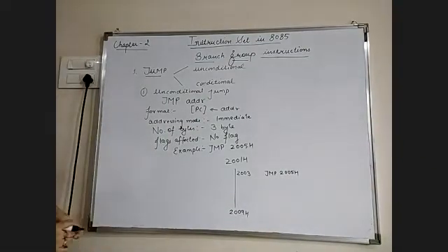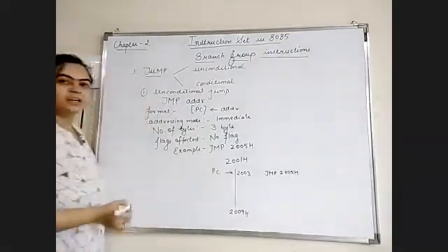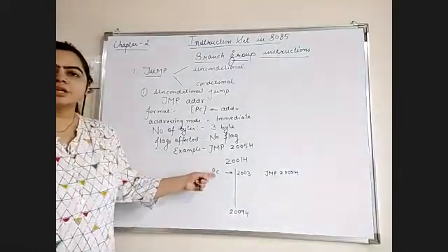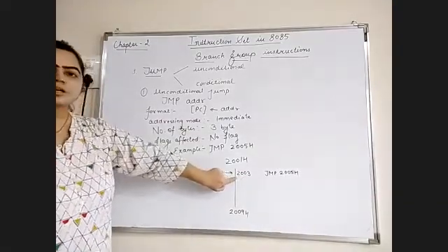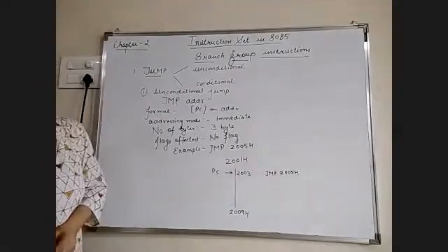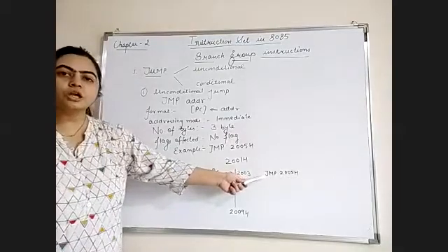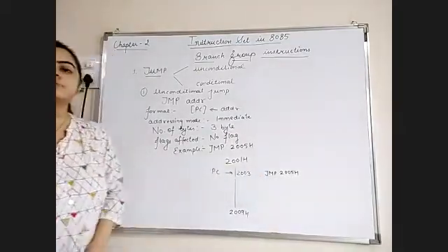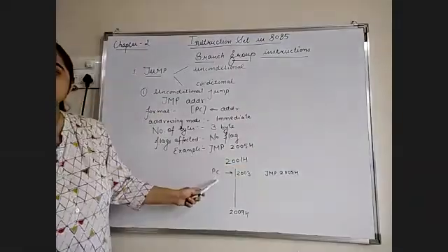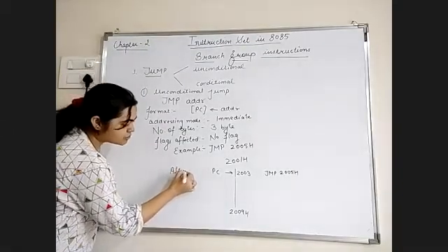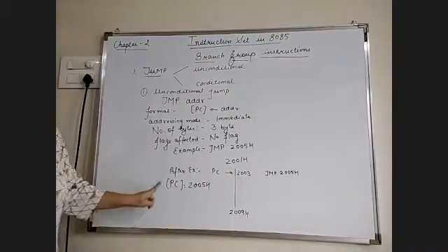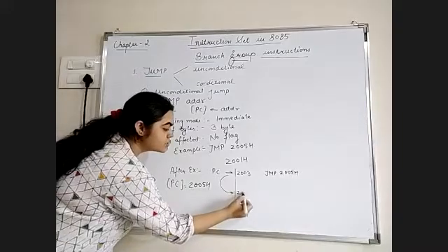Initially the program counter is at this memory location, because the program counter holds the address of the instruction which the microprocessor is executing. So currently the program counter has contents 2003H. Once the microprocessor comes to this branch instruction, it means jump to memory location 2005H. After fetching and decoding this instruction, the microprocessor first changes the contents of the program counter to 2005H, and then immediately jumps to memory location 2005H.